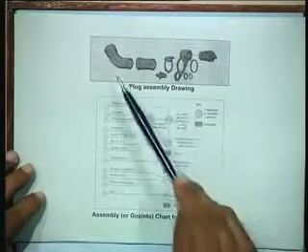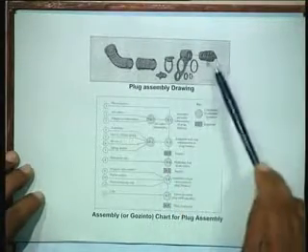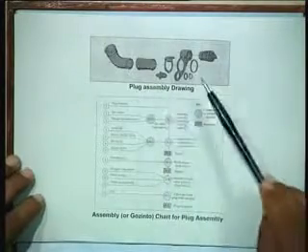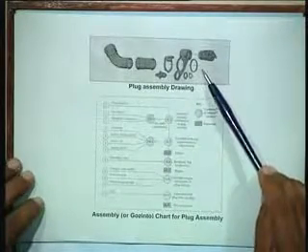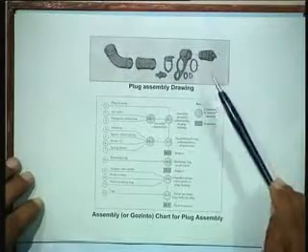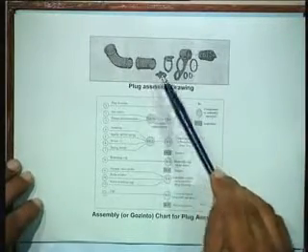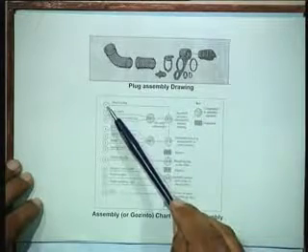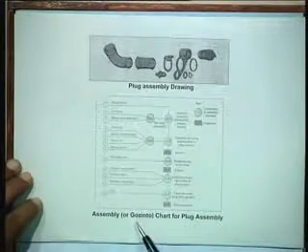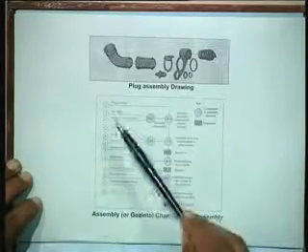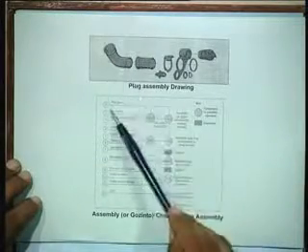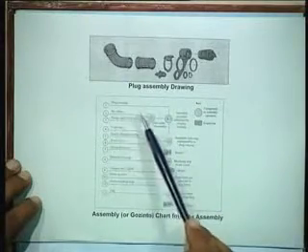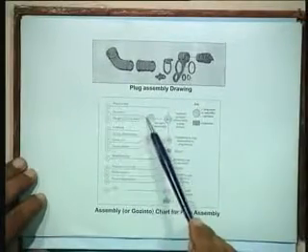For instance, if a component like a plug assembly drawing is available, and this is the product which we have to make, what would normally happen is that the various components which go to make the entire assembly would be shown here in an assembly chart. For instance, the plug housing is here, and on the plug housing, the first thing that is done is the air outlet and the flange air connection.